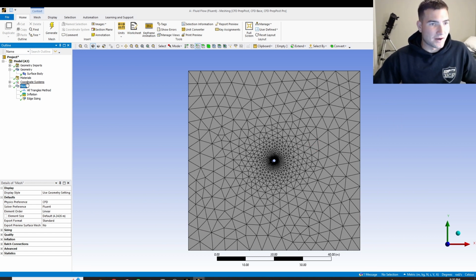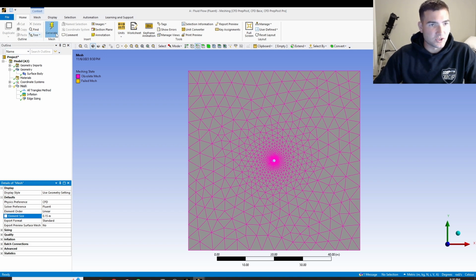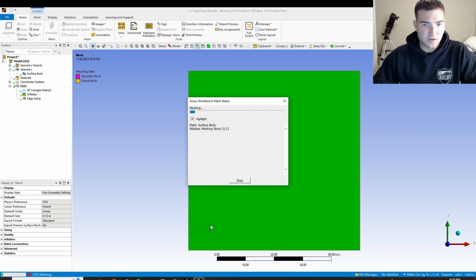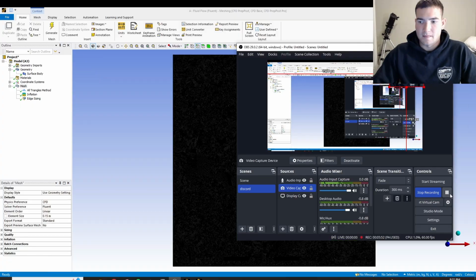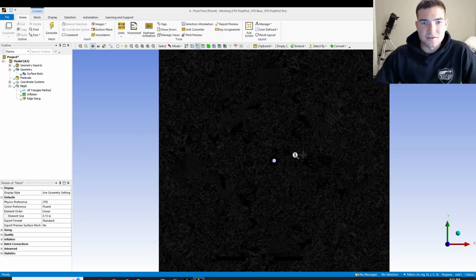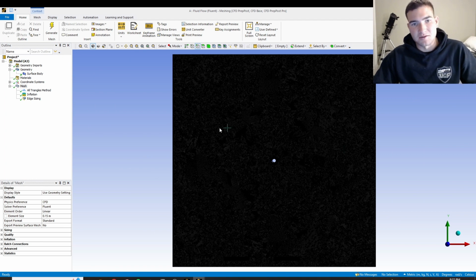So that's where we're going to go to our general mesh element size. I used 0.15 meters. And we'll generate that. And this is where we'll get our really nice fine mesh. Look at our progress. All right, so that took a little bit longer than I wanted it to. This honestly looks finer than what I did in my project for some reason. I used the same dimensions and everything, so it is what it is.